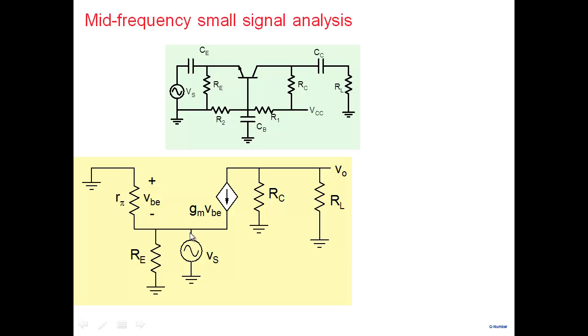So this is the schematic here, and I'm not going to sit down and derive it for you. You can see it very easily. If Vs is here, you can see that Vs is nothing but minus VBE. So the arrow will turn up. It will become gmVs, and gmVs flows through a parallel combination of RC parallel RL, and that's where you end up with a gain of gm (RC parallel RL). gm we know is ICQ by VT. So if you look at this expression, you see the gain is, in terms of its magnitude, exactly the same as the common emitter amplifier. Same gain, except that there's a positive sign. There's no phase shift between the input and the output. One should not forget that. So that's Av, the same gain as the common emitter amplifier.